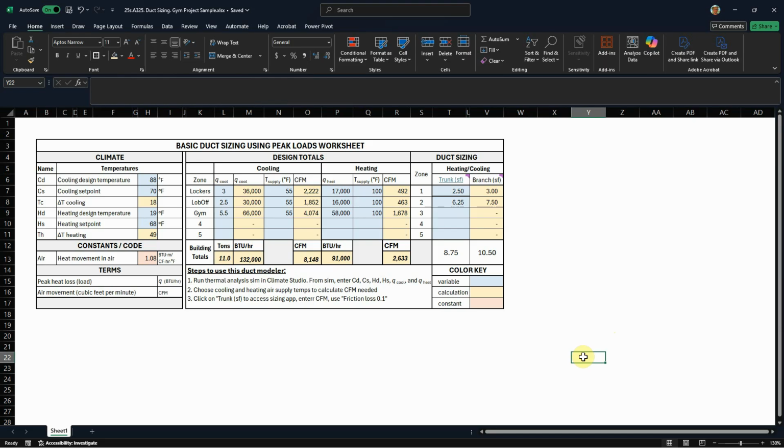If you were trying to accurately do this, I didn't even do this one yet, so that's even wrong. I don't remember. I don't want to actually do it. I think we're saying it was about 4 square feet, right? Because it was like 2 feet by 2 feet. Then if you were really trying to figure out your branching, you would say, okay, off of this trunk, I'm going to have my branch ducts. If I've got 8 of them, I get to divide the 4.8 by 8 to see how big each branch needs to be.